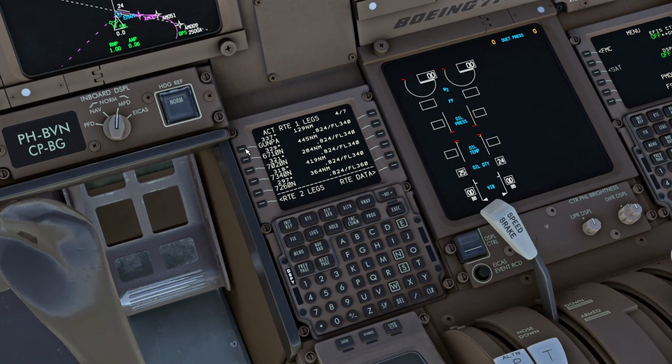As this is an oceanic flight, we'll be using not just waypoints but also coordinates, and as you can see in the flight plan overview, you just have to cross-check whether those coordinates are correct, and it's also important to check these kinds of coordinates that are between two latitudes. So this one is, for example, between 68 north and 67 north. Make sure they are correctly entered, these halfway latitudes.